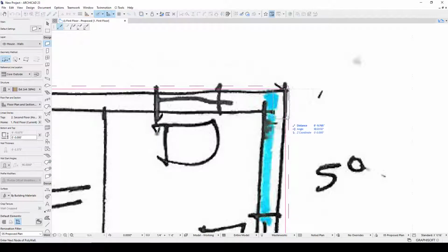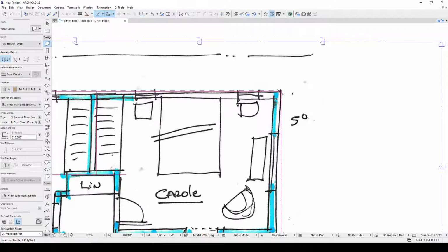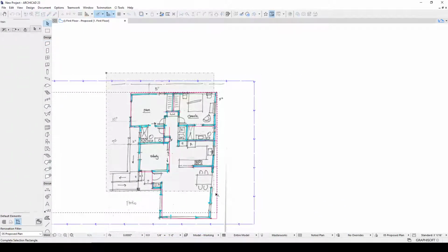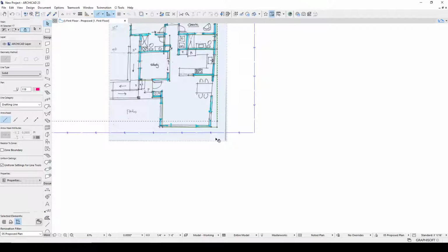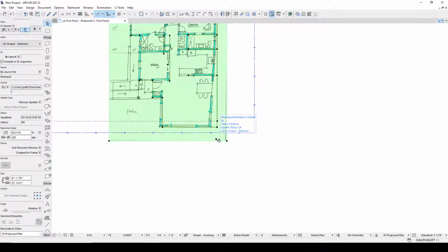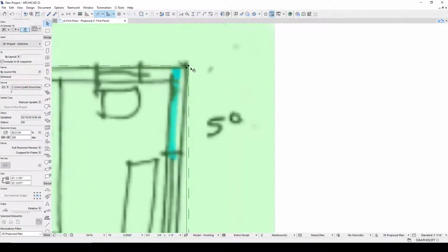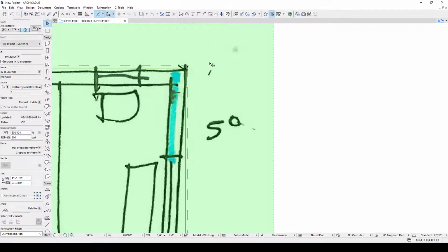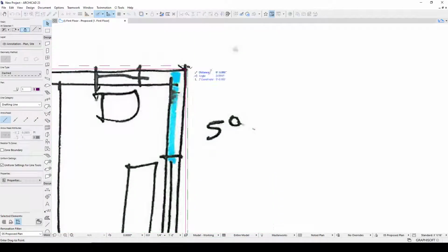I want to make sure. Now notice that because of so let's deal with that right now. Because we have the face of stud is where we're going to be dimensioning, I'm going to temporarily unlock these elements, Shift right bracket, and I'm going to F5, I'm going to move -0.5 inches and -0.5 inches. And that's going to give me enough room for the stucco. Oops, I moved my...